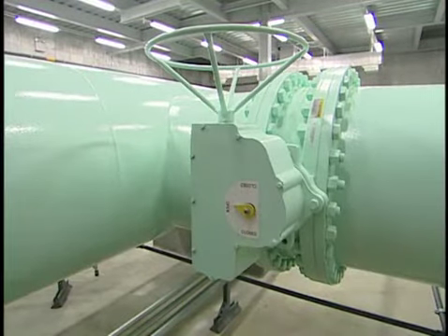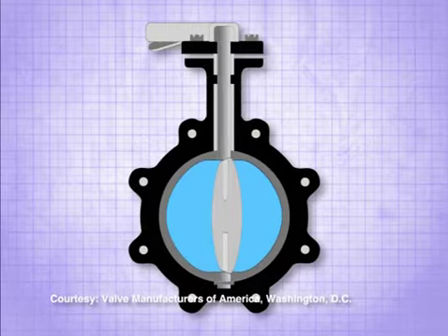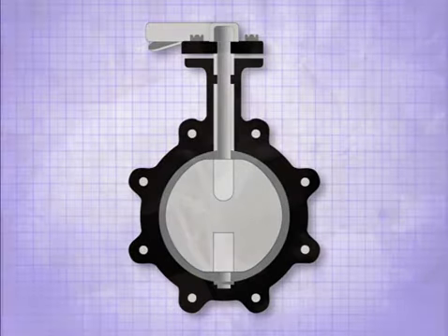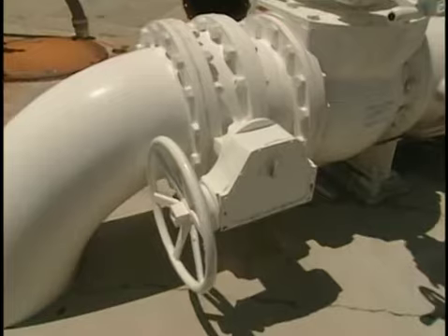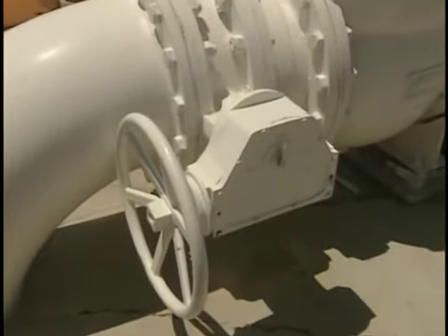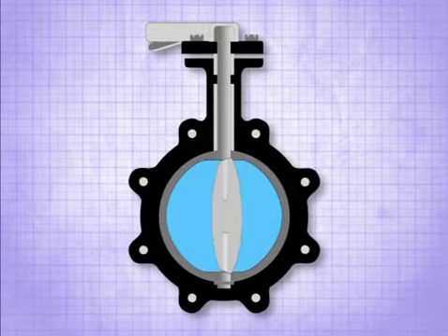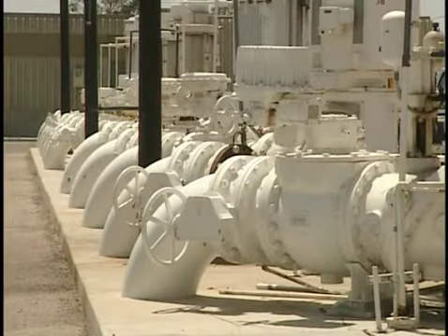A butterfly valve has a disc that is rotated on a shaft. When open, the disc is parallel with the flow. When closed, it is perpendicular to water flow and blocks water flow. Butterfly valves operate quickly and easily since the pressure on the two halves of the disc is relatively balanced and only 1/4 turn is necessary to open or shut them unless a gear reduction operator is installed. On the other hand, care must be taken not to close the valve too quickly and cause water hammer.